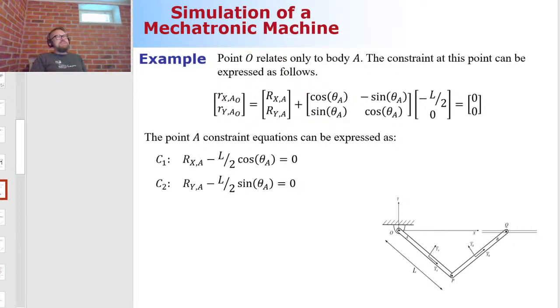97, 97. So that's good. That's very nice. Okay, so let's take a look. Let's make these constraints. The first one is a revolute joint that connects this beam-like body A to ground at this point.